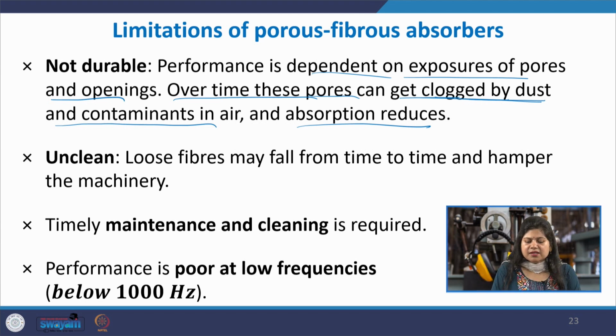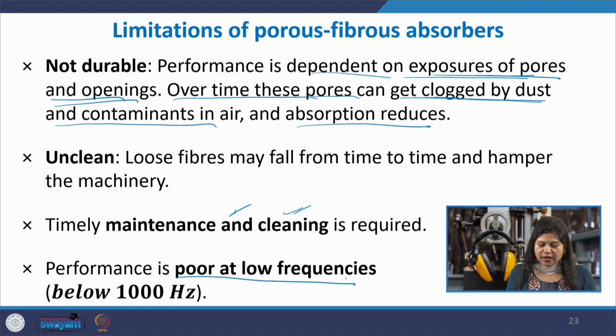Then timely maintenance and cleaning is definitely required, because of the tendency of the pores and the openings to get clogged with persistent usage due to the contamination from the air. And the last limitation is that they have poor absorption at low frequencies, typically below 1000 Hertz.